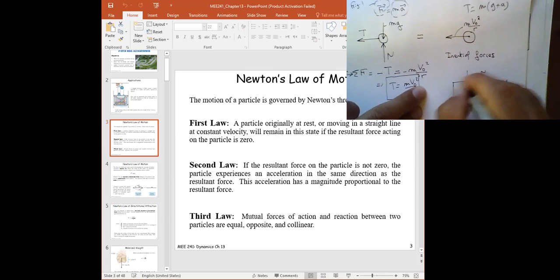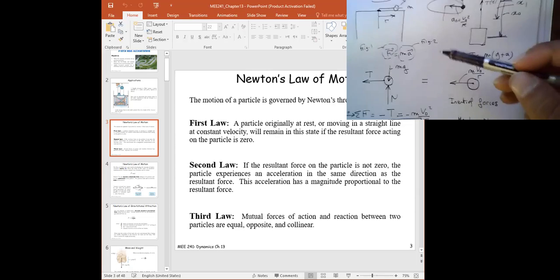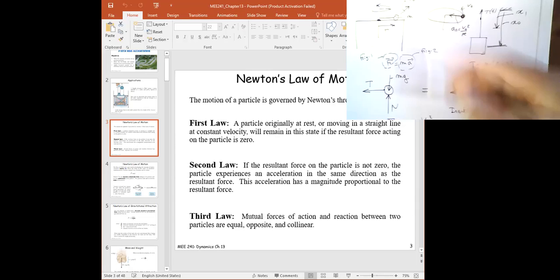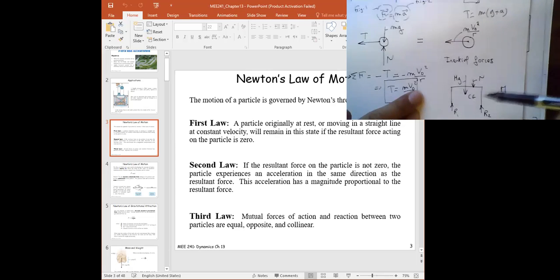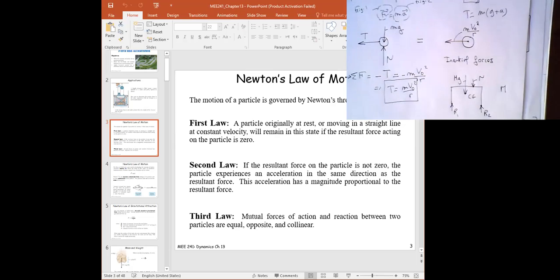So this is the free body diagram on a table, and this is the mass of the table. Put mg at the CG of the table, and then N is what? Equal and opposite, right? So if I'm doing a free body diagram on the ball, I'm putting N here, and then this N is actually also the same N on the table, okay? This is how later on you'll be able to analyze multi-body systems, or multi-link systems.